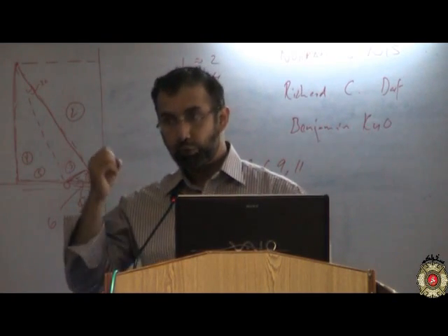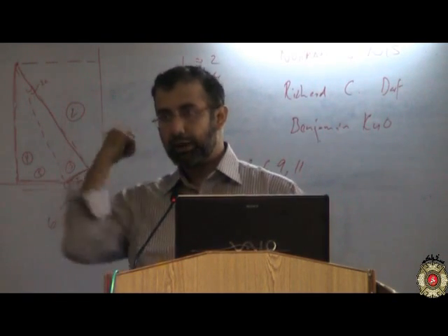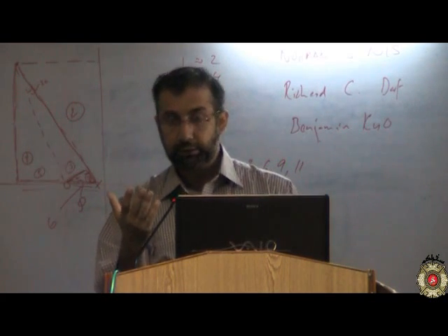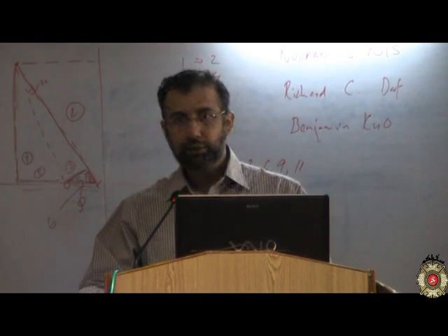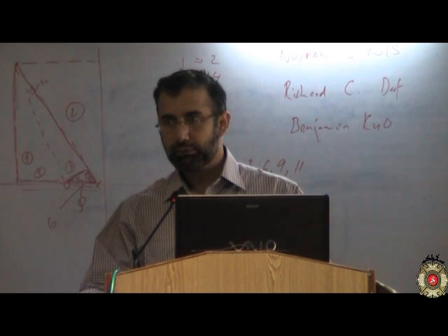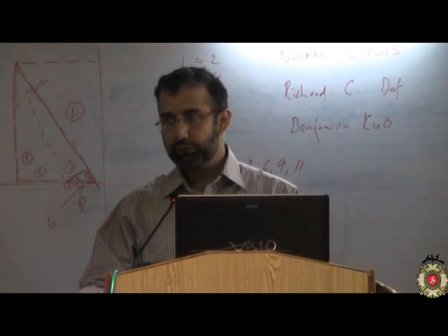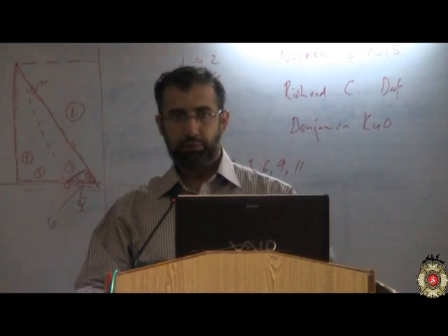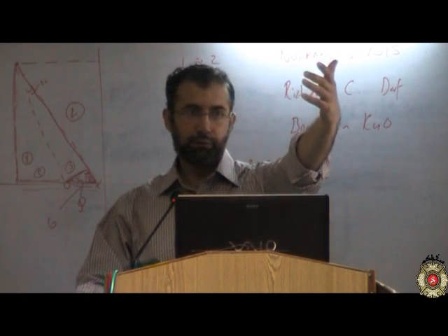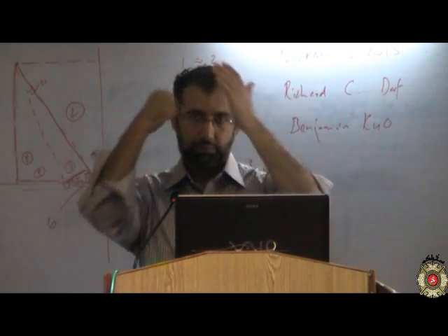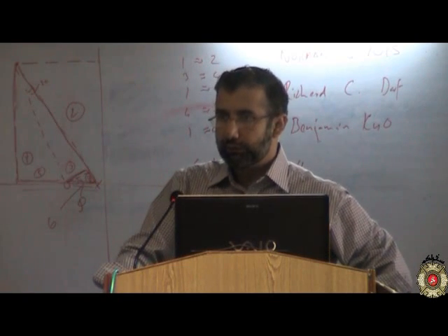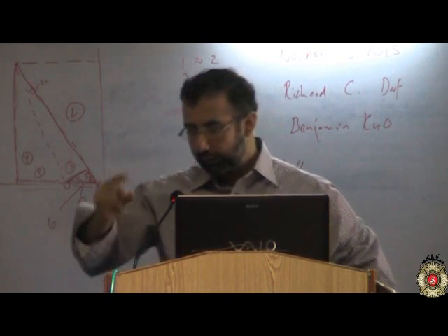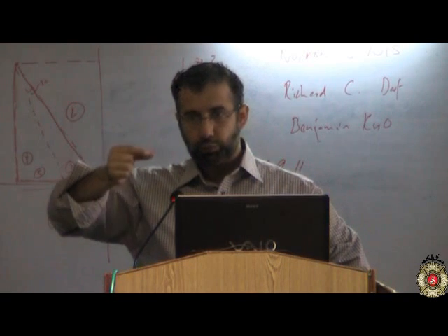If I am moving faster than the speed of sound, then I'll crash into that body, and then I'll realize that there was a body up there, right? That is why you have shocks. The shock wave is generated because the particles in front have no clue that something is coming, and there is a big variation in pressure, density, and temperature over a very small distance.